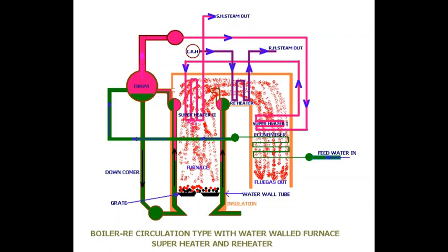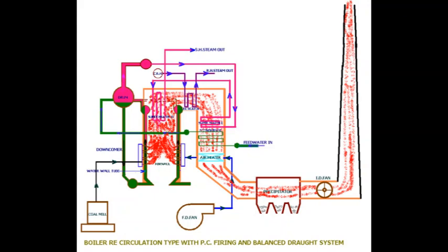With this arrangement, it was also observed that the requirement of oxygen has to be met sufficiently so that combustion can be completed and ensured that complete combustion has taken place, for optimum generation of heat and absorption and transfer of heat within the heat traps. So naturally there was the introduction of air preheaters and the arrangement of supply of primary air and secondary air.